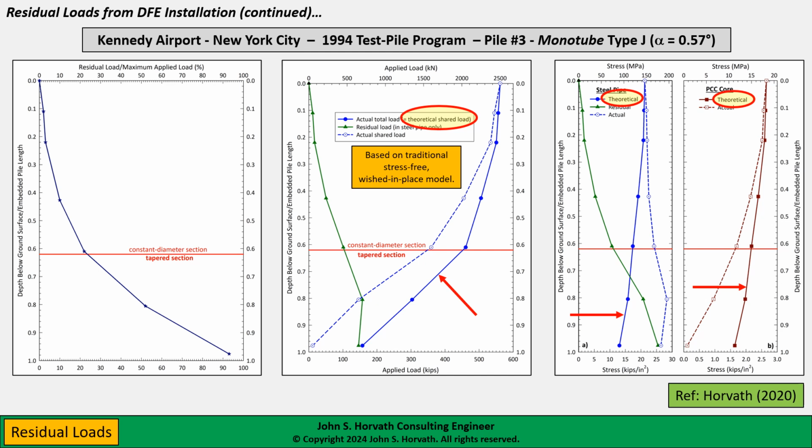And every time I've ever done this calculation in the past, and just about everybody I've ever seen do this calculation, always assume that both the concrete and the steel start from a zero stress starting point. So this assumes that the stresses in the steel pipe and the concrete core are zero initially. They both strain the same amount, and then it's a straightforward calculation to figure out how the stresses are apportioned between the two materials.